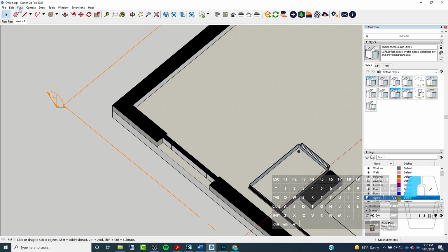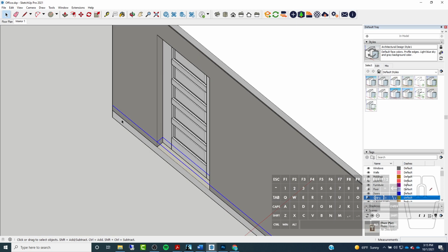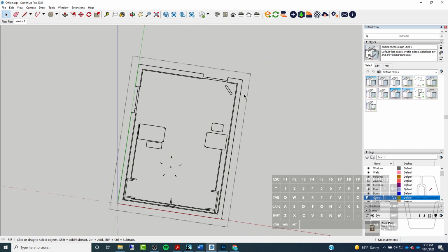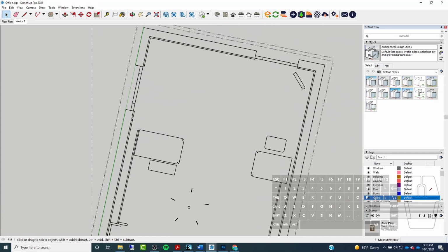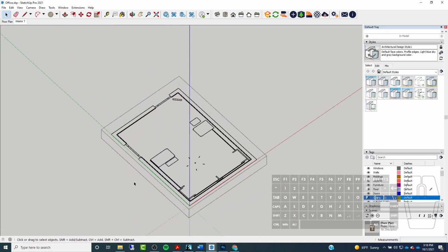It's probably going to be easier though if you just hide all of this. So now you can see that line there. And if you click on it, now you just have a 2D drawing of everything that it cut through, right? So I can see the cabinets, the desk and everything, and the dividers and all that on the floor plan, and all the doors and the openings and the casings and stuff. So that's really cool. That's a really useful feature actually. And then you can just export this group out as a 2D AutoCAD drawing into something like Revit if you wanted to do that.